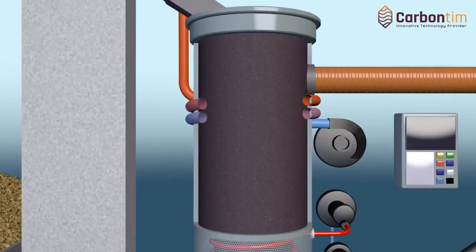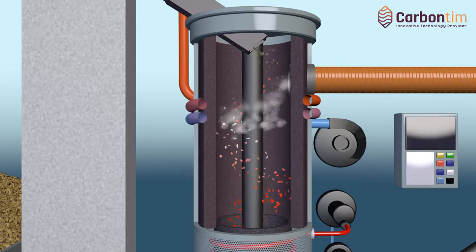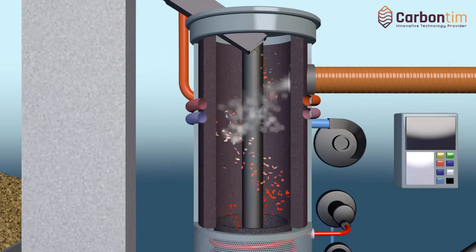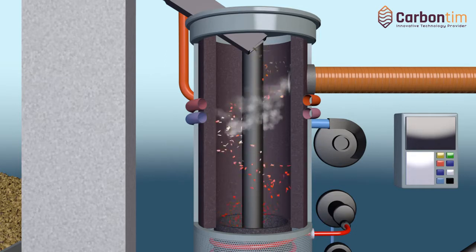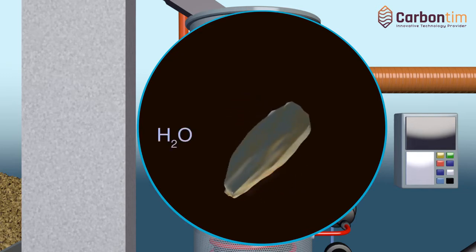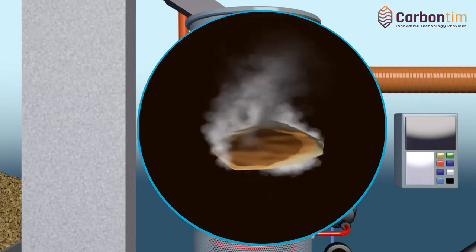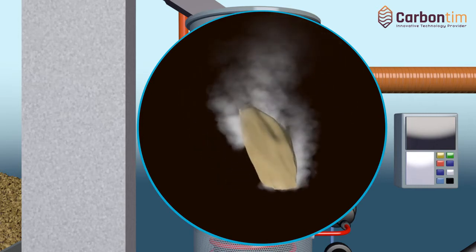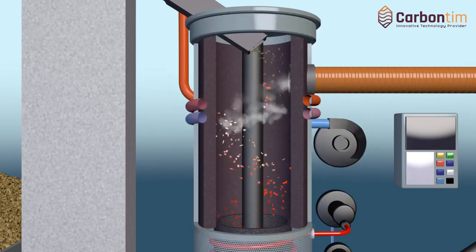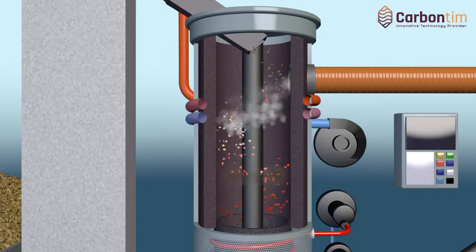Biochar production. Pre-dried and preheated biomass then goes to the pyrolysis reactor, where the following 4 processes take place. The moisture evaporation process. All the moisture accumulated in the raw biomass has to evaporate in order to initiate the carbonization process. Depending on the type of biomass and the amount of moisture accumulated in the process material, it can take from several to more than a dozen seconds, and its efficiency is due to the high temperature in the upper part of the reactor.